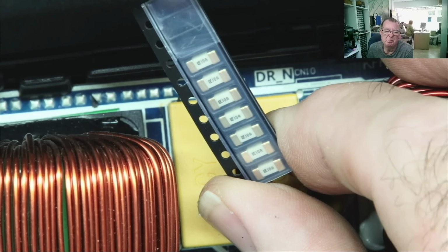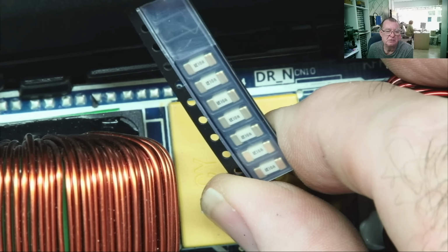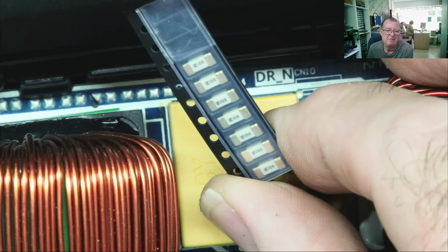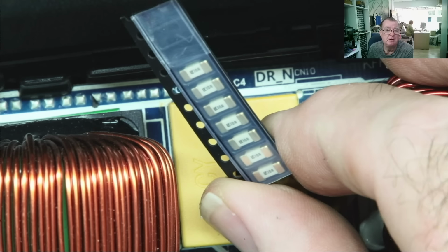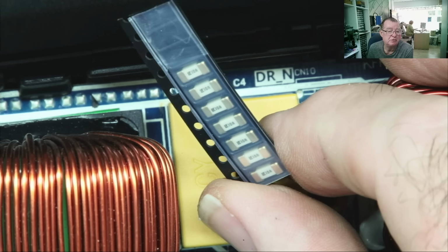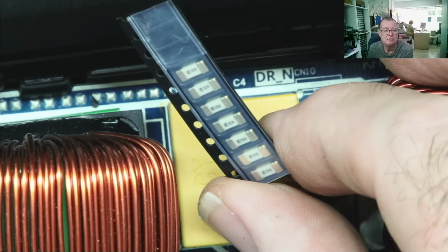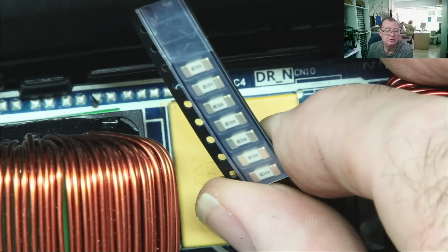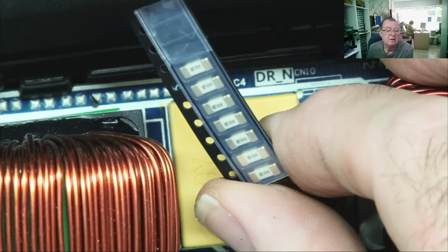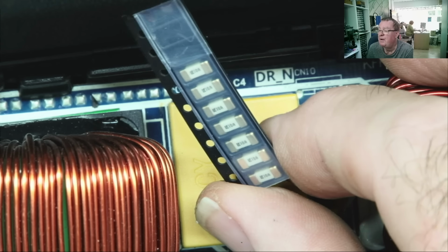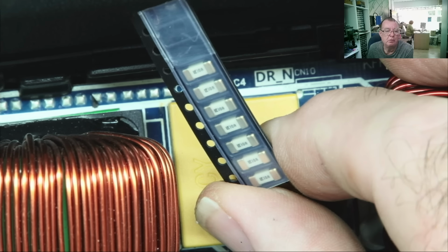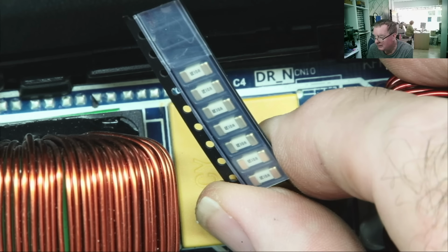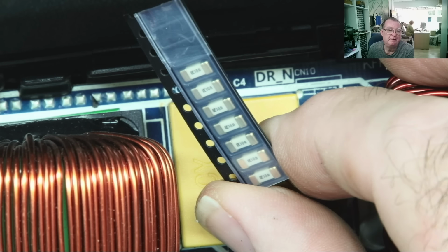One which is just broken, you can see the wire inside is just broken. Sometimes they just effectively give up, and you may find the device works once you replace the fuse. It could be caused by something that was connected to the device, of course, and now it's not connected. Replace the fuse and it works. So with fuses, if you find a faulty fuse, then it's probably caused by some other fault, and always replace the fuse with the correct type.